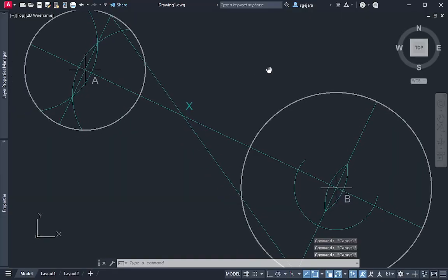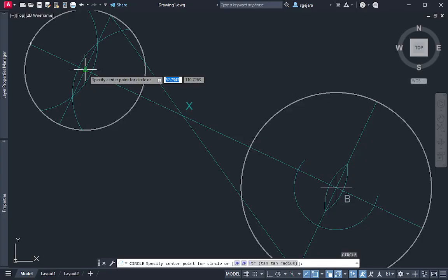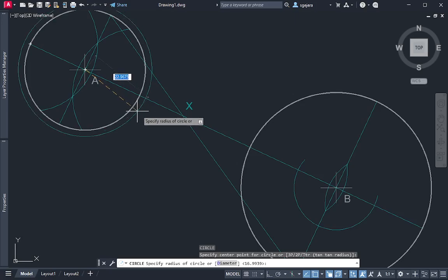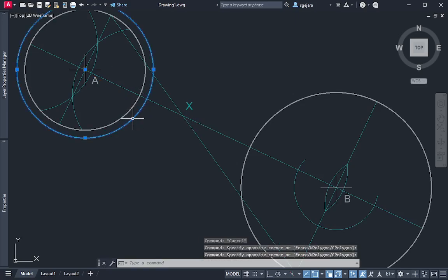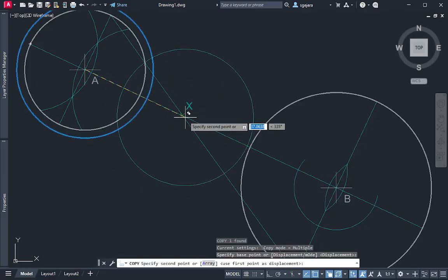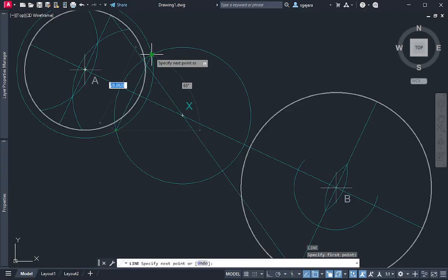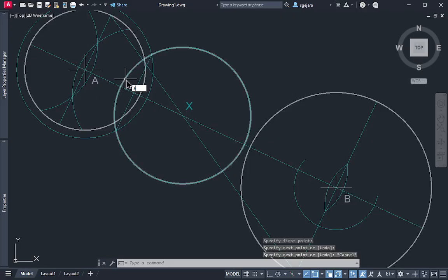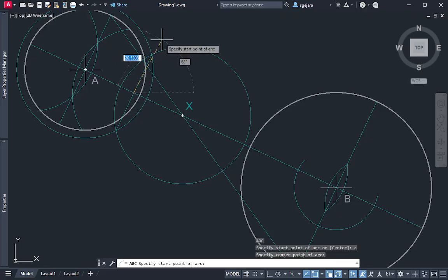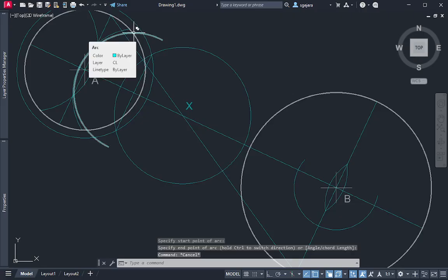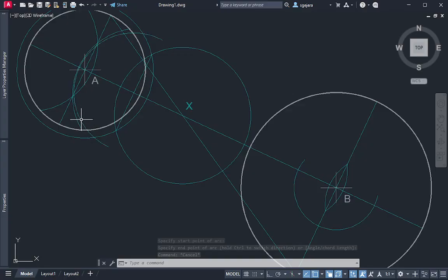And I'll do both, no? So kunwari dito sa left side, I'll do the scenario wherein geometric constructions ang gagamitin ko. So if I were to do geometric constructions, what I'll do is I'll find slightly larger, siguro ganyan. Copy this one onto the other side. This is the perpendicular bisector. So this point right here, I can create an arc from here, like so. Where it intersects, yan yung tangent point. Ito tangent point dito, and ito yung tangent point dito.